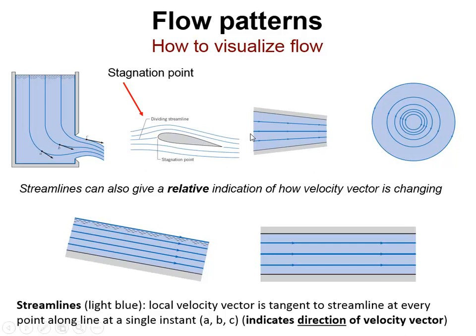The velocity is increasing not over time, but as the flow moves from left to right. And there's acceleration here too. Remember that velocity is a vector, and it has both magnitude and direction. And so in this rotational flow, as the water flows around in a circle, there is an acceleration because the direction of the velocity is changing over time. The streamlines aren't parallel, but it's not because it's speeding up, it's because the direction of the velocity changes as it flows in that rotational manner.